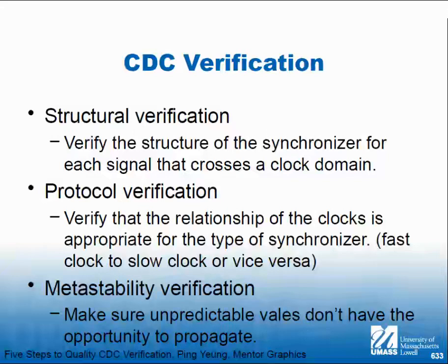Because that's how many you need. That means you have 2 extra states. You do something with those 2 extra states, so if you accidentally got in one of them, you would return to normal operation, right? So that's metastability. That's extremely difficult to test, by the way, because you're testing a state that there's no legal way to get into. So how do verification engineers deal with that?